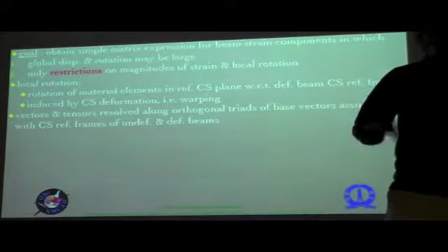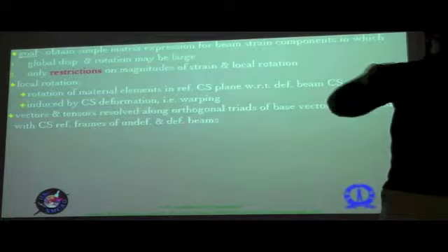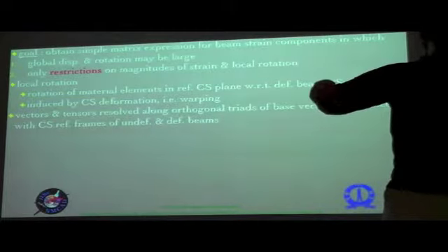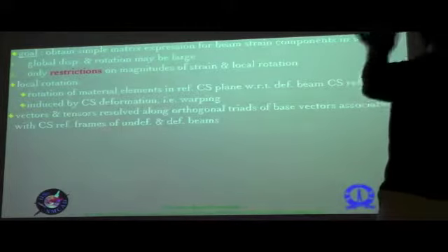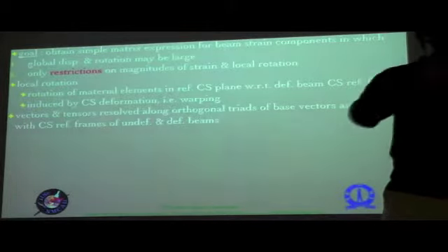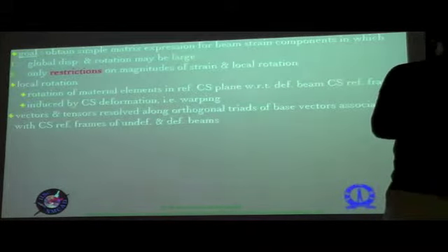Okay. It becomes very, very difficult to derive a theory for beams made out of hyperelastic materials which can take strains of the order of 1, or typically 400%, etc. In such situations, you have to completely eliminate that small parameter and deal only with the geometric small parameters.